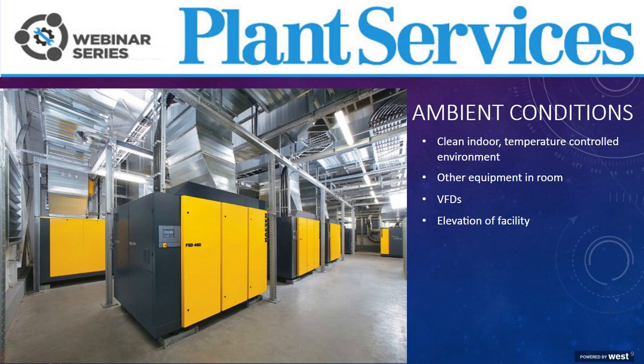To sum up the points we've discussed regarding ambient conditions, strive for installations which are located indoors in clean, temperature-controlled environments. It's crucial to have easy access to the equipment. The location of the compressor room is also important, as is what other equipment might be placed in that room. Finally, one thing that we haven't really mentioned is to consider VFDs and maybe the vulnerability of a VFD prior to installation, as to whether or not your designated install location is going to be hospitable for those kind of drives.